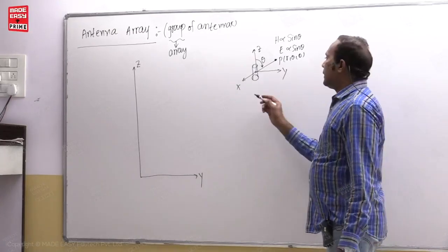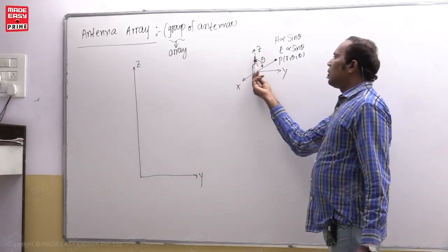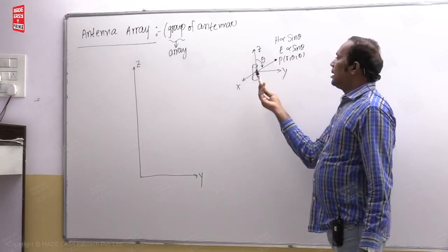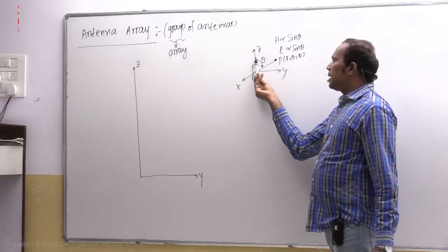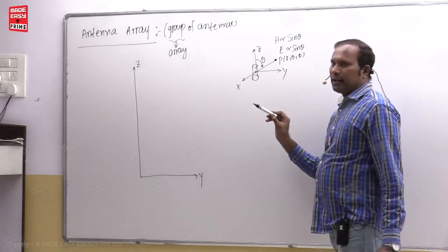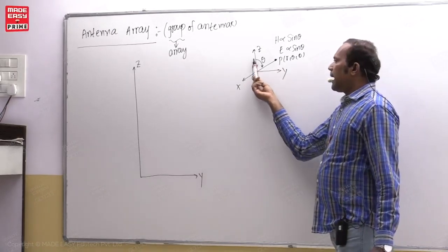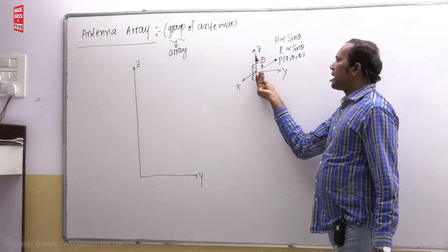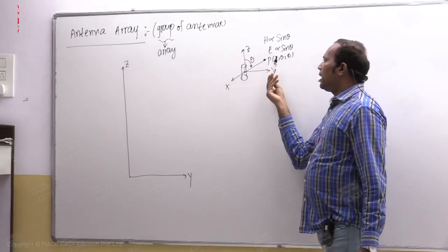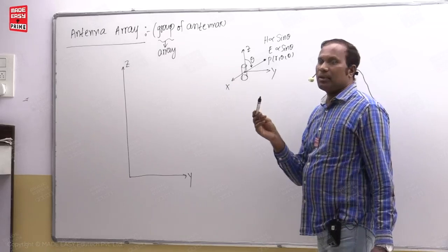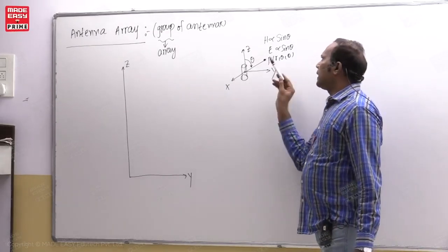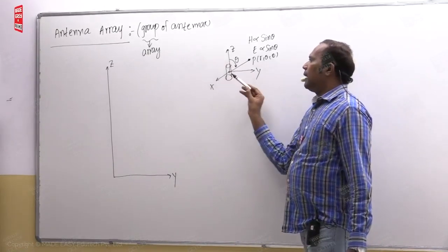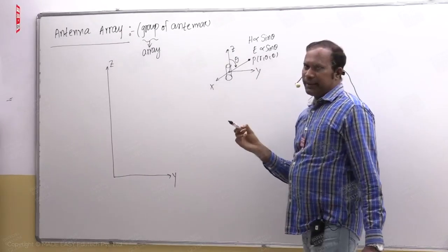This antenna rod was also parallel to the z axis, since in the derivation the rod length was in the z direction only. So in the spherical coordinate system theta means the angle between the z axis and point P. But after the derivation, theta means the angle between the antenna rod length and the line drawn from the origin to the field point.